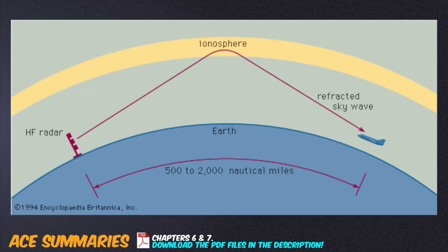High frequency or HF transmissions are used for long distance communications between two specific points. It uses predictable propagation paths, often refracted off the Earth's ionosphere over large distances. The pilot will choose frequencies within this band of 2 to 22 MHz, depending on the distance to its target receiver. Higher frequencies give a greater range.